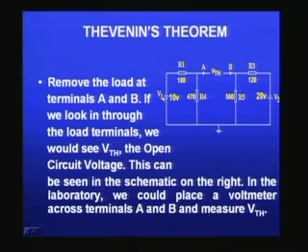And similarly, measurement of Thevenin's resistance also is very simple. Remove the voltage source by a short, this voltage source also by a short, and measure what is the resistance between A and B using a multimeter in resistance range. So, as simple as that. Now, but we will go ahead and then try to see how we can calculate.